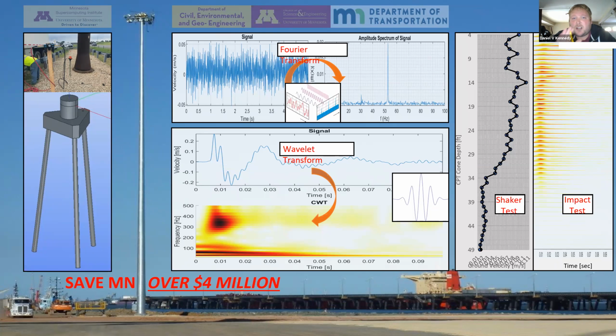You can see this in the middle on the top image. We take a shaker and secure it to the top, or to a steel rod in contact with the pile cap, hopefully directly over the pile. This in turn shakes the pile in the ground. This is done at different depths next to the pile. We take that signal in time, use a Fourier transform to convert it to the frequency spectrum, and that gives the amplitude of the ground motion at that testing depth.